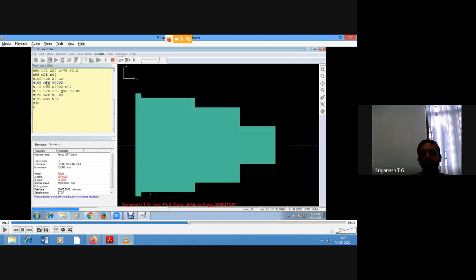So we have sent the tool back to its home position, and now it is reading the line M06, change tool. Insert the second tool T0202. Then click on next motion once again. So it reads the next line M03 S2500. That is, start the spindle and let it rotate at 2500 RPM, and M07 for coolant on. Yes, next is what? The next line is G70, finish turning operation.